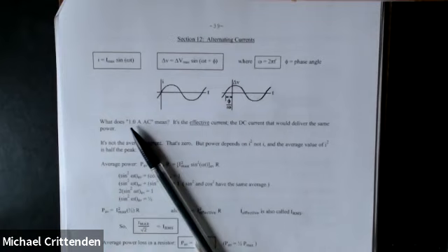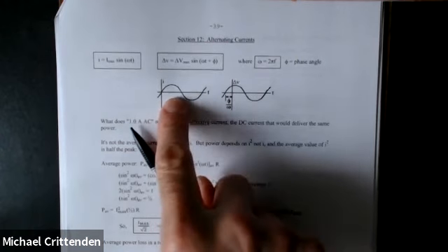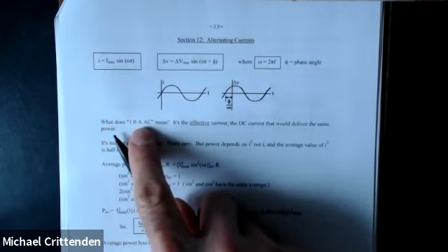If you got 10 car batteries and hooked them up in series so that you had 120 volts of direct current, just like your 120 volts of house current, and you hooked your lamp up to that, and 1 amp is going up the cord, that variable voltage, or variable current, that you get from your household outlet would make the bulb exactly as bright as if you had a steady 1 amp of DC.